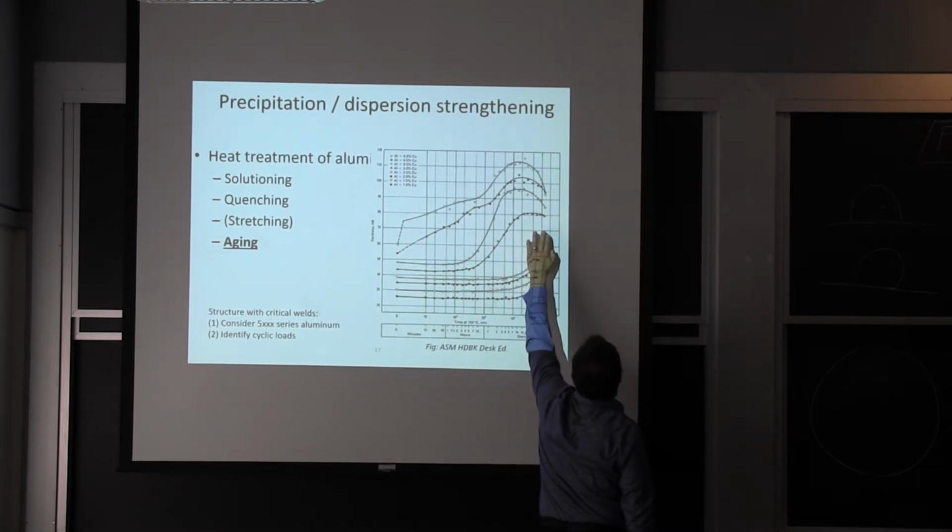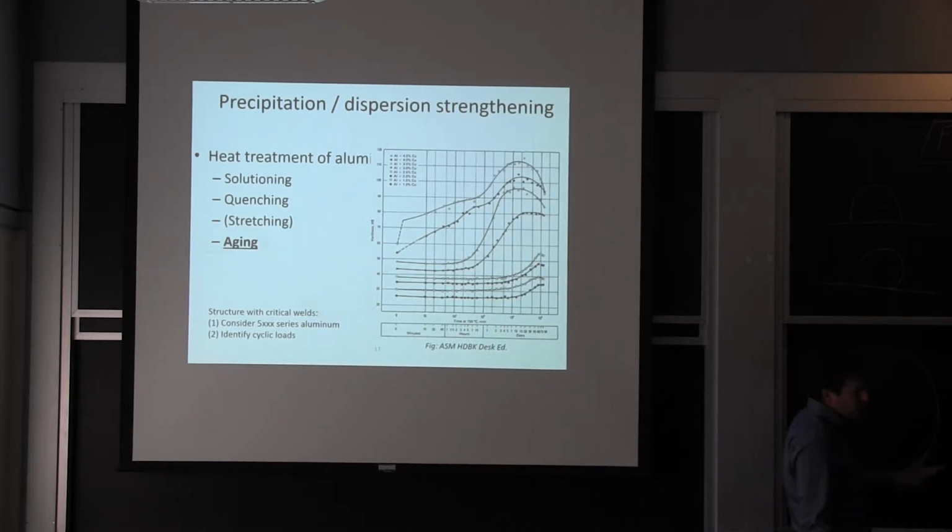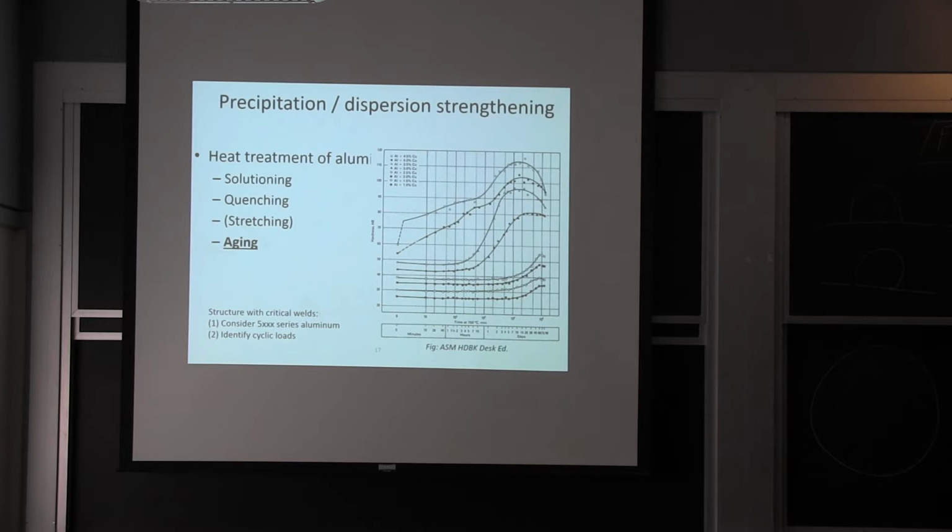And later down, when you reach a certain size, and these are the second or third generation, they are semi-coherent. So they will stretch the lattice in one direction sometimes and not in the other. And that's the size that happens to slow down the dislocations the most.